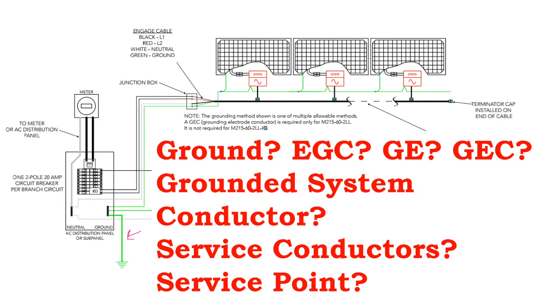I get scared on my grounding electrodes because I use clamps instead of welds to connect to this electrode. Recently I've been doing CAD weld for ground rods, and I really like how that process makes a much more secure connection. On mine, I will go and install a secondary ground rod on the project site with a secondary clamp, just because I'm afraid of these clamps becoming insecure with time.